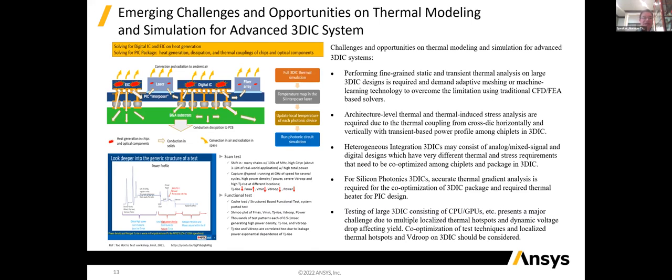For testing, that's another challenge. We are looking at a millisecond. The dynamic thermal hotspot will move from one IP to the other IP, and this will happen very quickly. So this will impact your test sequence and also the test frequency. And that will contribute directly to the increase of the temperature locally and also to the dynamic voltage drop locally. So when you run the testing on the Teradyne or the Advantest, you need to know where your peak transition temperature is occurring.